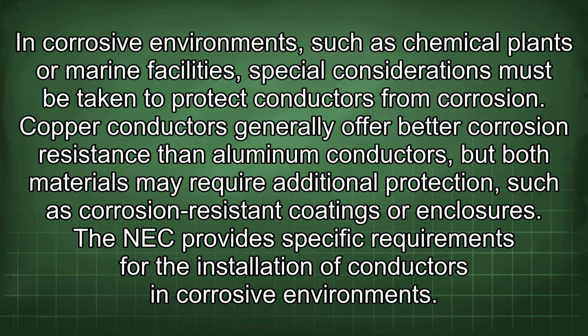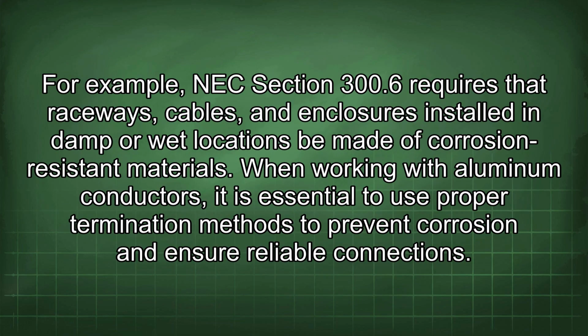In corrosive environments, such as chemical plants or marine facilities, special considerations must be taken to protect conductors from corrosion. Copper conductors generally offer better corrosion resistance than aluminum conductors, but both materials may require additional protection, such as corrosion-resistant coatings or enclosures. The NEC provides specific requirements for the installation of conductors in corrosive environments. For example, NEC Section 300.6 requires that raceways, cables, and enclosures installed in damp or wet locations be made of